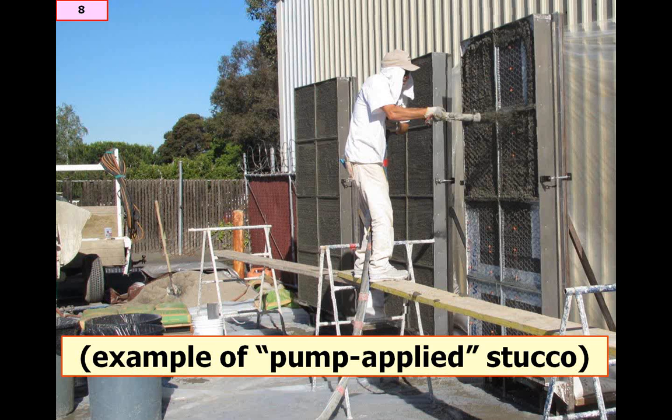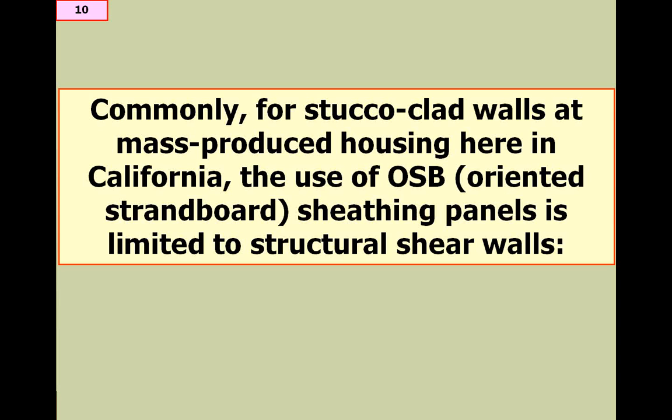And another point of interest as we move along: for mass-produced housing here in California, and I'm sure in lots of other areas, the use of sheathing panels, whether it's OSB or plywood, is limited to the structural shear walls. I used to work in Seattle and up in the Pacific Northwest, where all walls were sheathed. But here in California, even though our area is so earthquake prone, for some reason we allow builders to apply their sheathing panels only in pre-designed locations. So here's an example of OSB sheathing at this project.